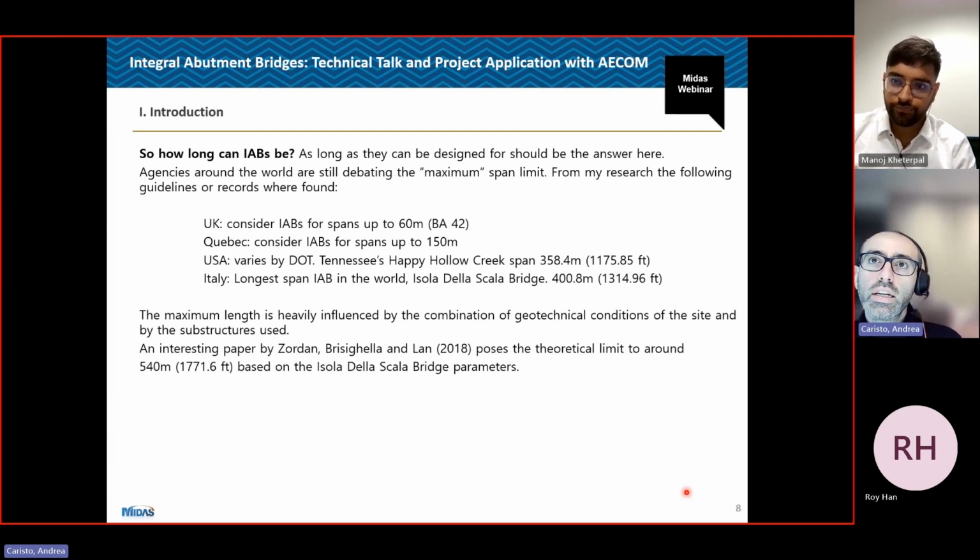Although there is an initial different response for the first 5 to 10 cycles, depending on whether the bridge is connected to the substructure and first undergoes an expansion and contraction cycle or a contraction and expansion cycle, over 120 years of life, that paper proved that there is virtually no difference to the bridge.